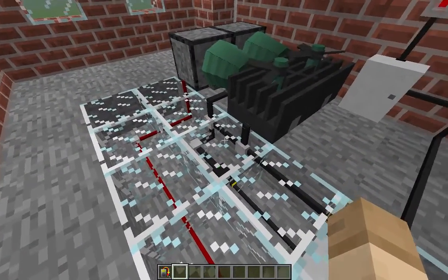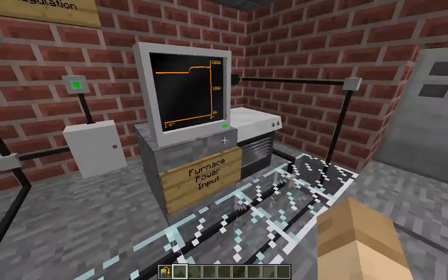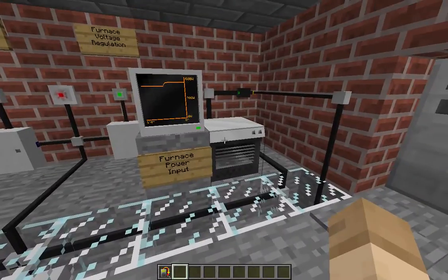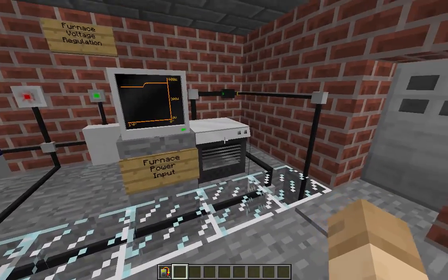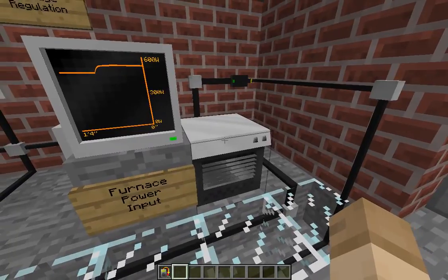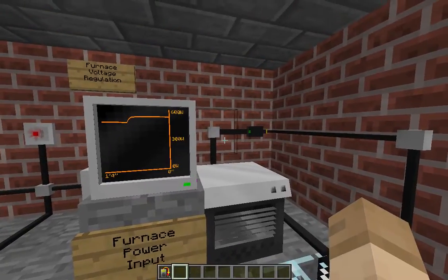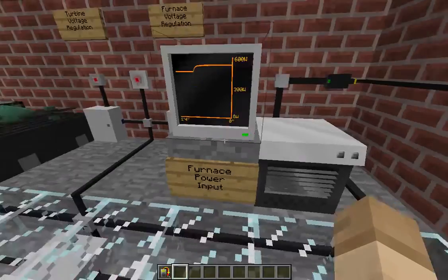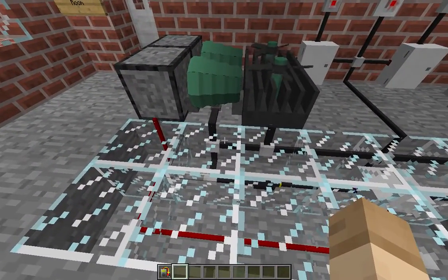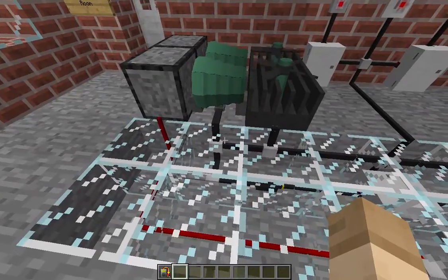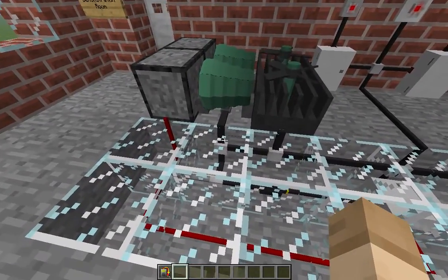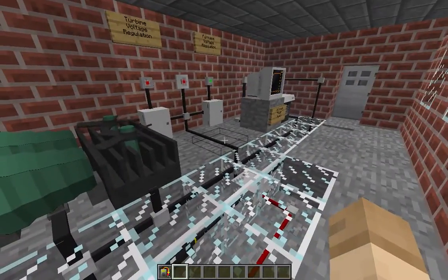losses. Now, this might be good in terms of fine-tuning devices and making sure you get exactly the amount of power you want at your locations of your components, but you have to remember that if it's between 50 to 55 volts here, it has to be at least 50 volts or greater here, or at least 55 volts or greater here, simply because it has to have a higher voltage and higher power here to make up for those cable losses.